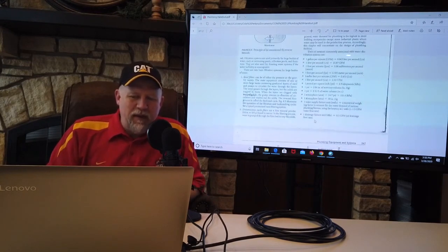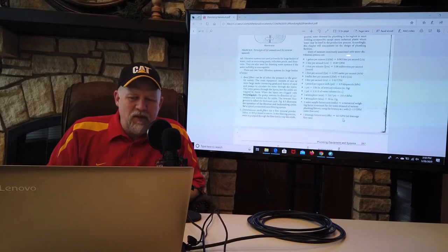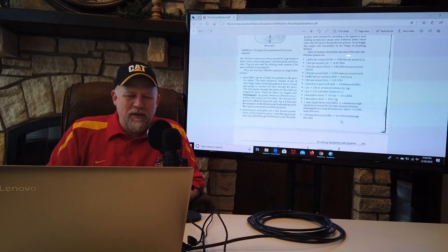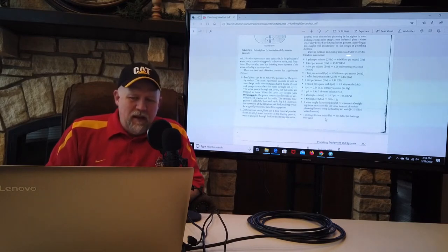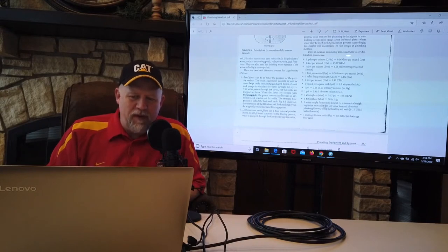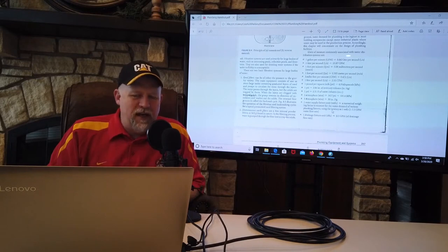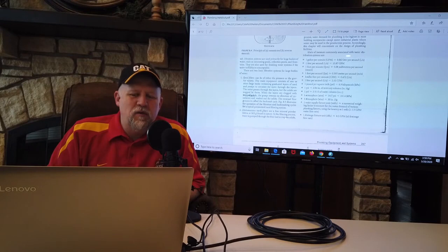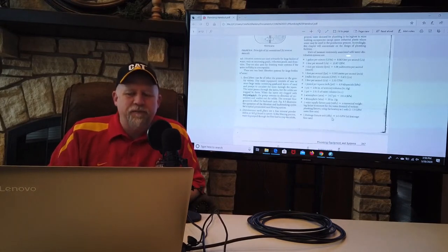If you go down to the last one on that page where it says 1 drainage fixture unit is approximately equal to 1/2 of a GPM at drainage flow rate, get rid of that. Absolutely positively erase that. Cross it off, whatever. Please do not ever use it. Also, the one above it, water supply fixture unit is about 1 to 1.5 GPM. Cross that out too. There's tables that we're going to use for that. Do not use those shortcuts. So cross those last two conversions off.